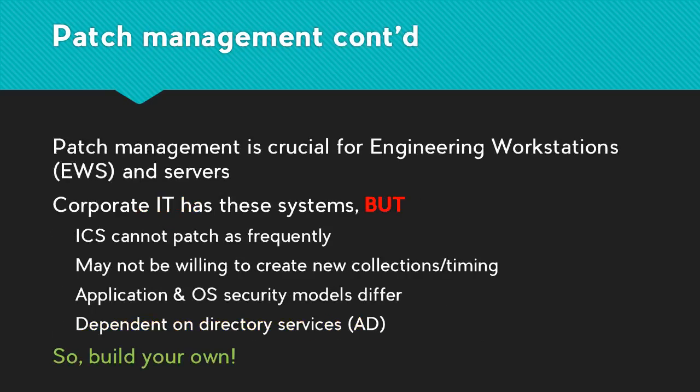So patch management, engineering workstations and servers, those are Windows boxes. You've got to patch those carefully. Again, corporate IT has these systems, but ICS can't patch it as often. They may not be willing or able to create new collections or timing on that. The application and the operating system security models are different between ICS patching and IT patching, and a lot of times depend upon Active Directory services. So what's the answer? You can actually build your own.